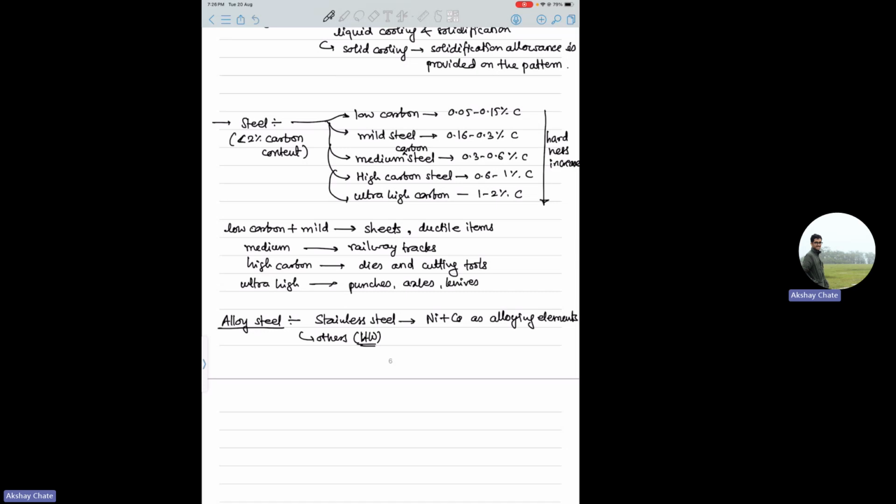So, since these are high melting point kind of metals or materials, you need to use dry molds, sometimes permanent molds, and ramming has to be very careful. Otherwise, at higher temperatures, if it is not properly rammed, there will be some defect, etc. We'll see certain defects next. So all those things are discussed in the class, and you can look into those.